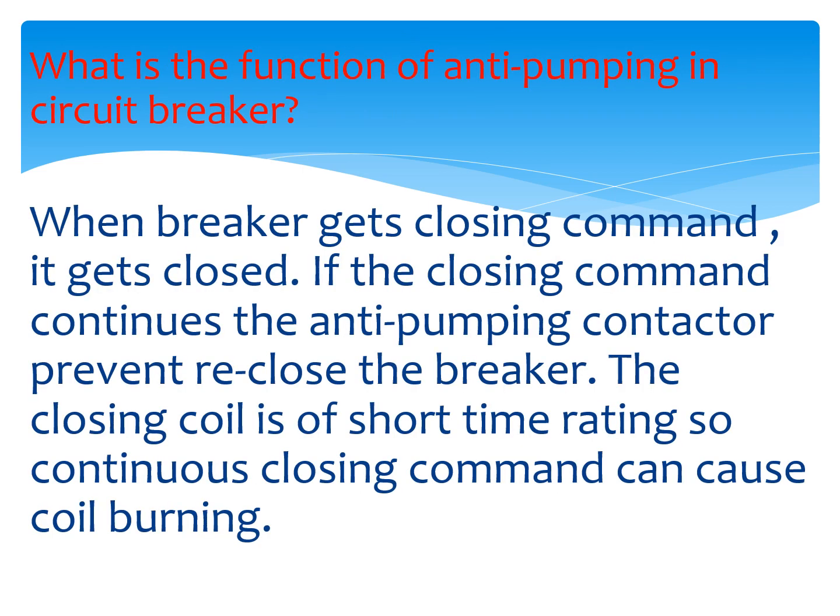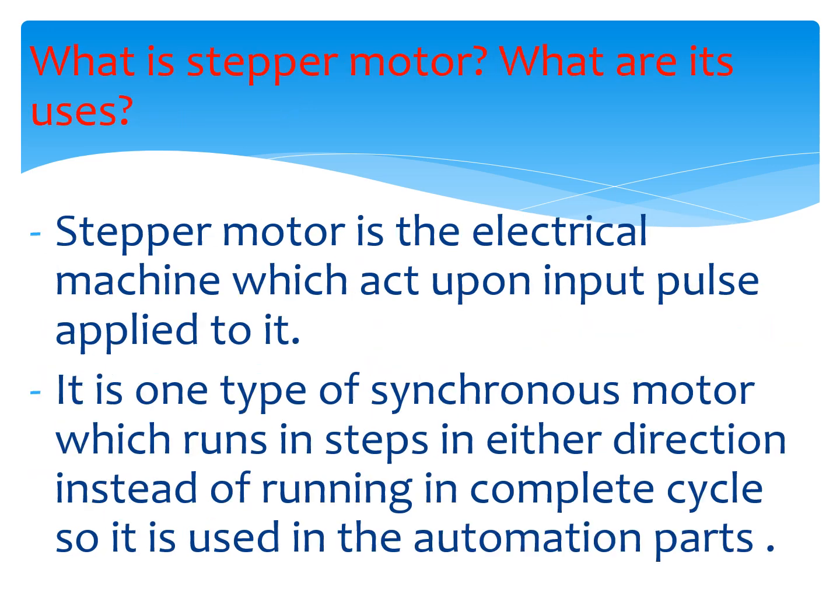What is the function of anti-pumping relay in the circuit breaker? When the breaker gets a closing command, it gets closed. If the closing command continues, the anti-pumping contactor prevents reclosing of the breaker or the continuous command to the closing coil, as the closing coil is of short time rating. So if there is a continuous closing command to the closing coil, the coil can get burned. Thus, anti-pumping saves the closing coil also.